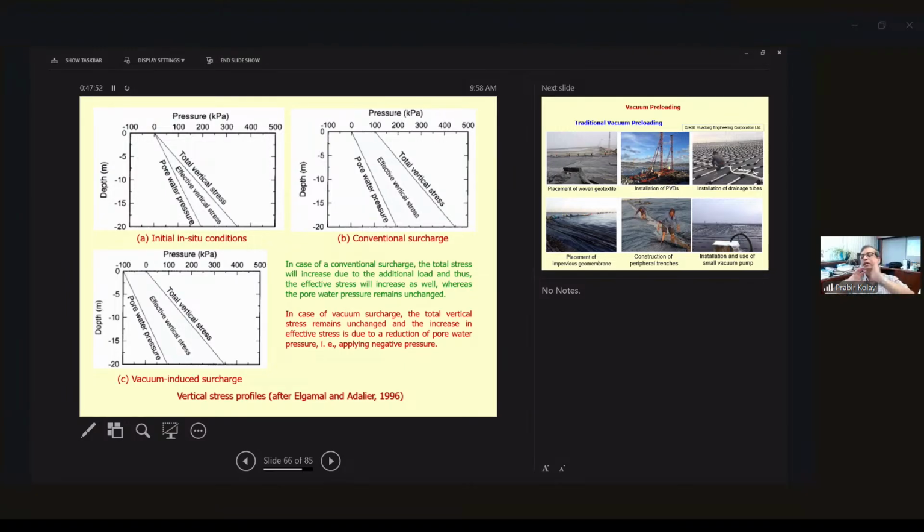Okay, for any type of soil, where is the strength coming from? For granular type of soil, the friction between the particles, right? Friction between the particles. More friction means more strength. That is for the granular, sandy type soil. For clay, more strength comes from more stickiness, correct? More cohesion. So now the thing is, pore pressure increase, meaning what? So you assume there is a soil particle, another soil particle. The pore pressure means water filled inside the voids of the pore space, right? So now pore pressure increase means what?